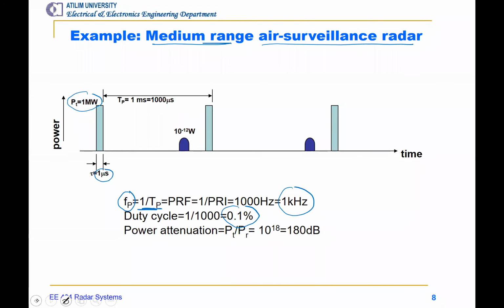But in some cases, this is not like that. For example, missile systems, where you have to trace every motion of the weapon, where you are transmitting continuously, illuminating continuously and receiving echo signals continuously, because even a very little time difference or error would matter. But mostly for surveillance radars, we transmit just 1% or less of the time.